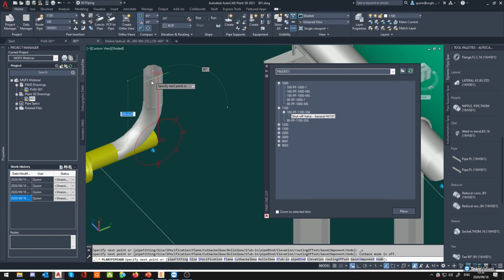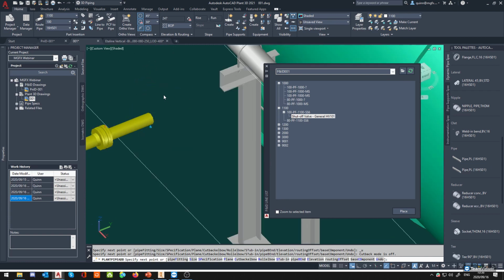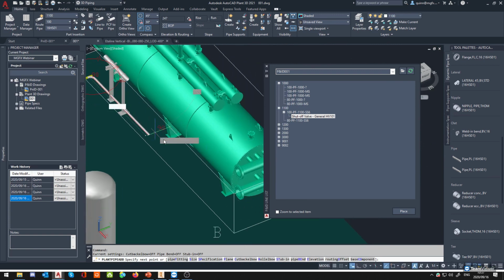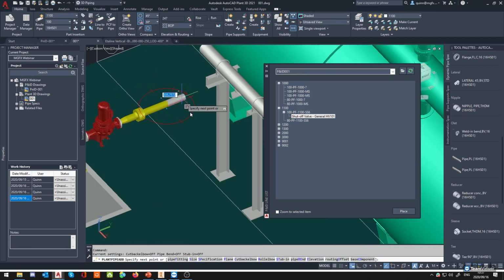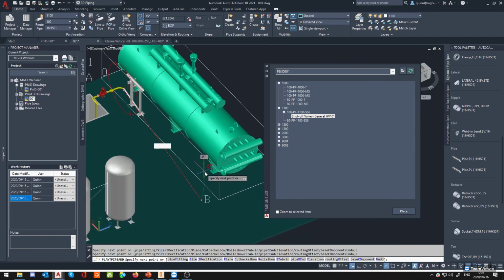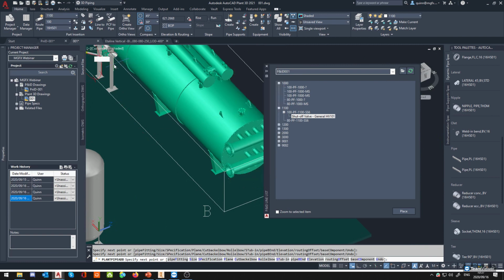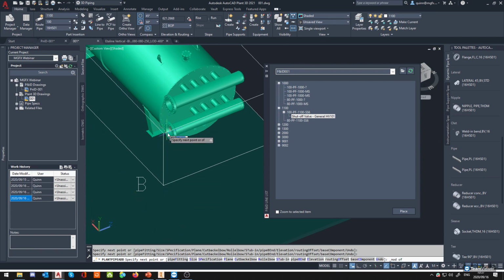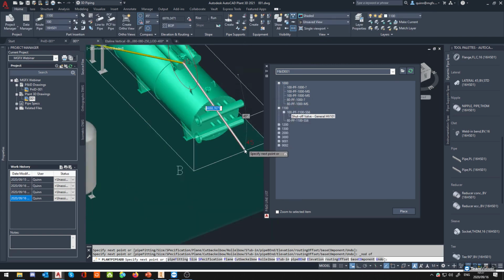So with this, it gives you quite a lot of flexibility in where you want to go and route around. Normally what I do, to be honest with you, is I don't use these subsections as much, because they can get a bit tricky to get them to do exactly what you want. What I'd normally do is I prefer to use the auto routing option, which would literally be picking from the endpoint, giving it a slight difference, normally staying about 45s, etc., rolling elbows, and then with that little piece routed up, then what I'll do is I'll take it to an endpoint.